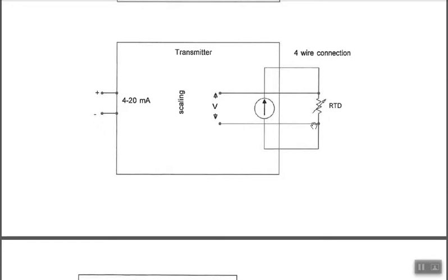Which probably raises a question in some people's minds when they're hearing that. Right away you might get asked, well, why do you need 2 wires going to the same place? And that gets back to the fact that one of those 2 is going to carry current to the RTD, while the other one just comes in to look at the voltage at that point. So the subtle distinction between the 2 white wires, for example, is that there is no distinction until you connect them to what you're going to connect them to. The distinction is then when one's carrying current, it's the current carrying white wire, and the other one is just the voltage sensing lead.